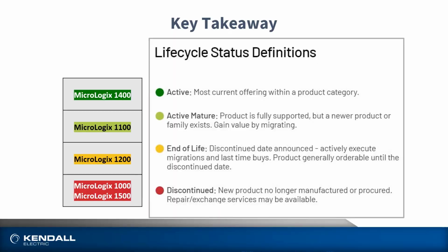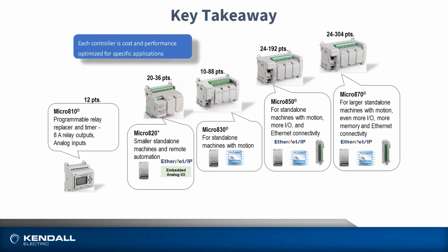Today we have learned MicroLogix controllers have a very defined lifecycle status. Apart from the MicroLogix 1400 and the MicroLogix 1100, all other MicroLogix controllers will either be end of life or discontinued by the end of 2021. Rockwell offers the Micro 800 family as the next generation of controllers for your applications.